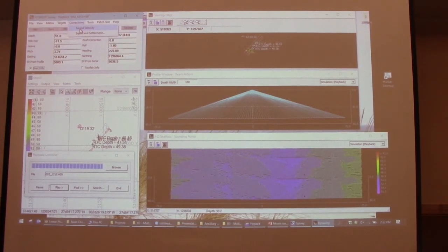So the first one you took, you load it in here before you started surveying, so it would flatten out the bottom. Okay, so if you get to a place where the sound velocity changes dramatically and you start to see it, the best way to do it is stop the survey, do your profile, then add it there. That's right. You want to try to keep the survey as genuine as possible, other than trying to do it at the very end. It makes your editing better, right? Am I correct?